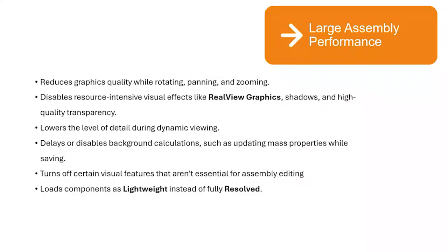And then in more technical terms, to translate that for you guys, lightweight opens your components, your features, your sub-assemblies, etc., as more of a graphics component along with its mates, instead of opening the sub-assembly, all of its parts, all of its features in its entirety. Okay, so that's just a quick explanation.